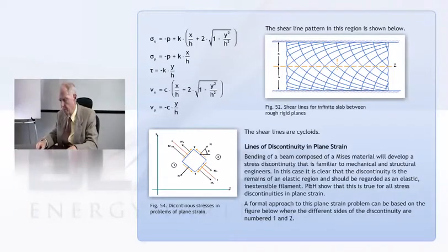Well, first, remember that this stuff is rigid until it has plastic flow. So nothing happens at first because you need to get the region fully plastic, because you know how a beam bends. And then when that happens, you have the normal stress on the top equal to tension, say, and the normal stress on the bottom equal to compression.